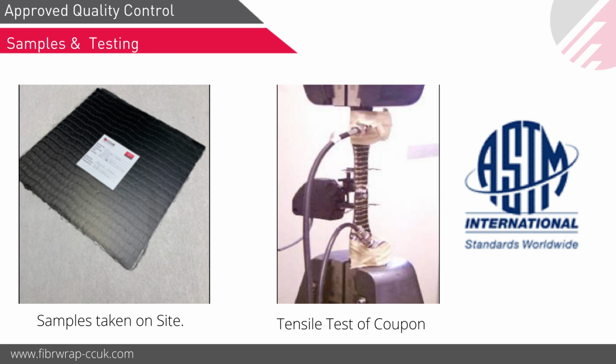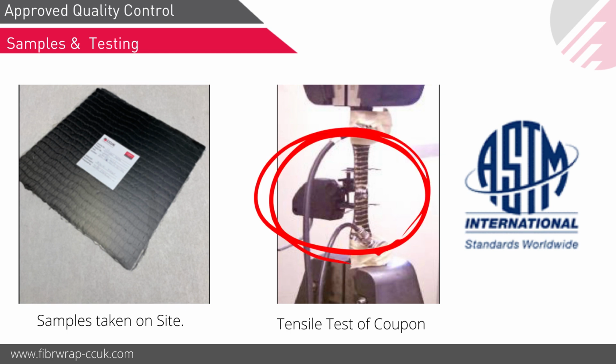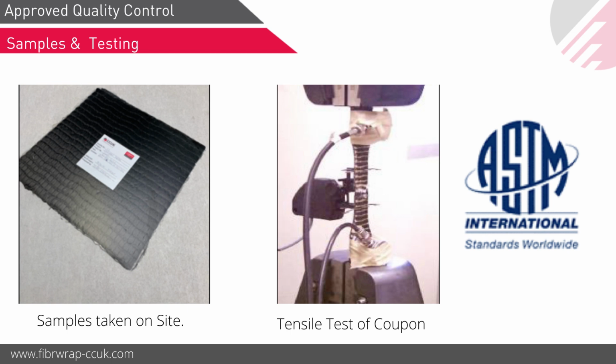And after that, you send it to an independent laboratory. They can cut a coupon out of it and do a tensile test. Those tensile properties should match with the data sheet of the material, or should match with your design values. So that's the pass criteria for that.